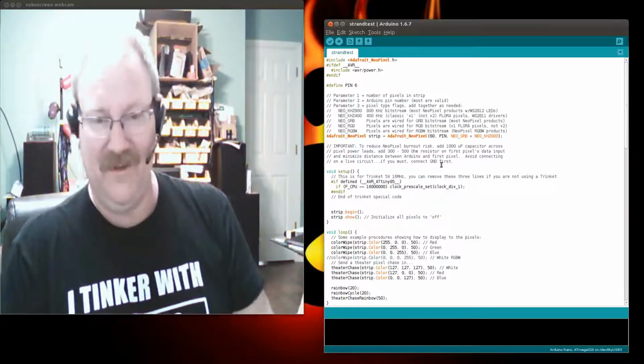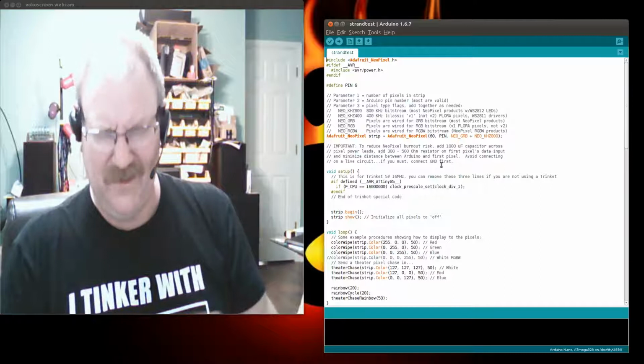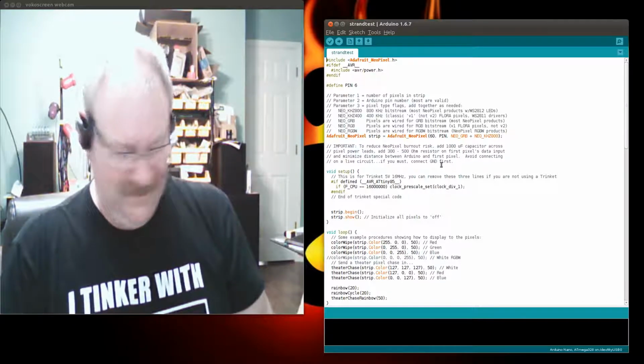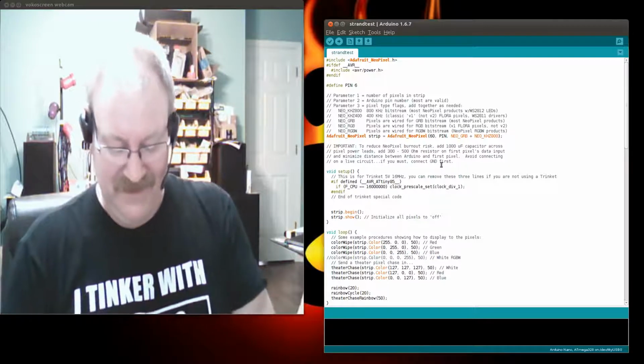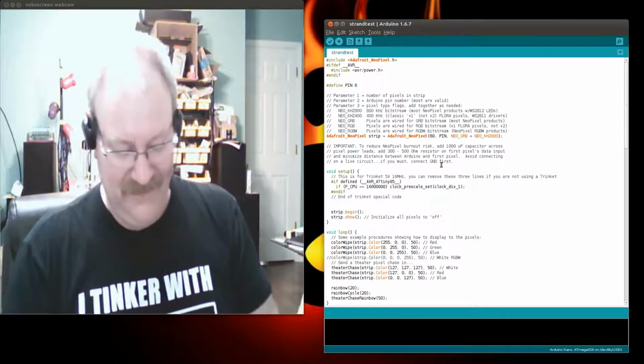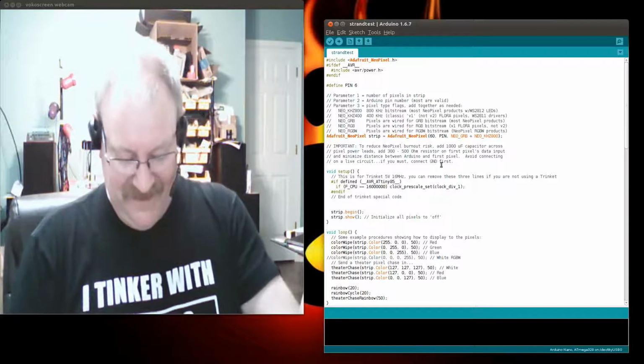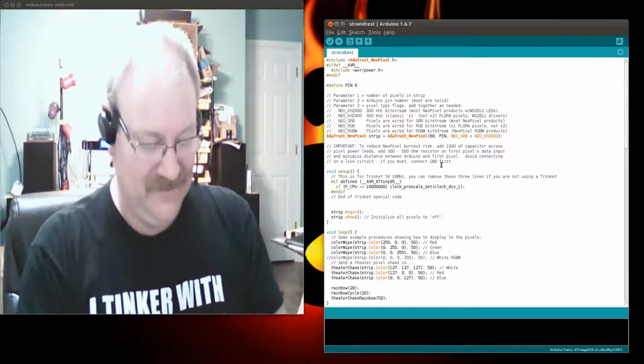And we put them all over the place because we partially want to get the hammering effect of the switching of these Neopixels and also the Maxim chips. They actually hammer a little bit as they're switching the LEDs on and off, and create voltage transients.